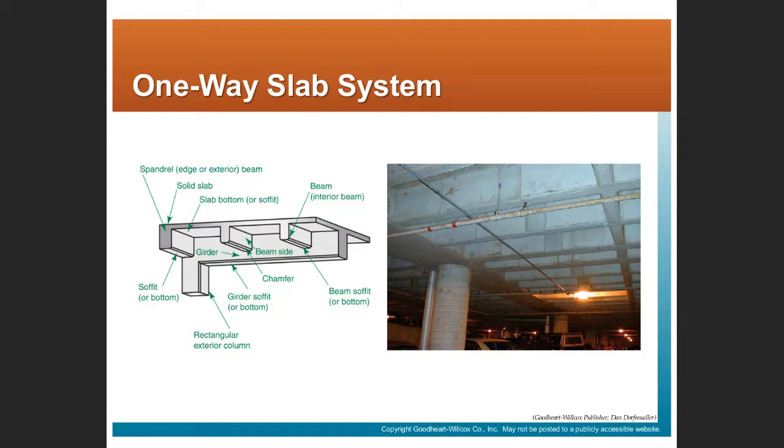Again, conceptually, this could be wood, right? The beams could be 2x6s or 2x10s, bearing on a concrete foundation wall, or they could be bearing on a steel I-beam, right? I think we have an I-beam running down the middle of the basement in both Sullivan. Certainly, I remember seeing that. Or this could be done in steel, right? It's conceptually very similar, whether we're doing it in wood or concrete and rebar or steel. We have loads being transferred from one member to another and ultimately being transferred to a column, and that column ultimately bearing on soil someplace. Does that make sense?